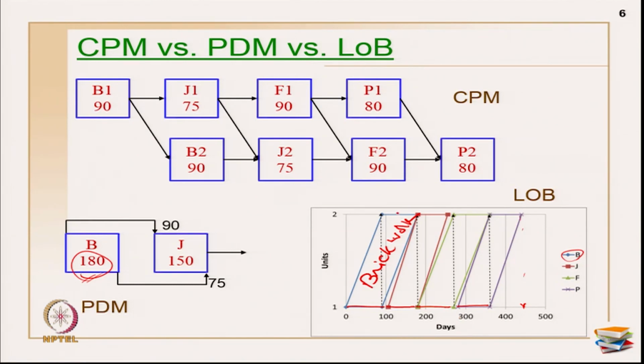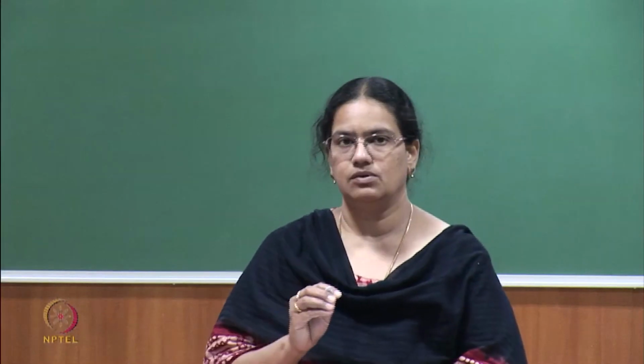The same thing is happening in unit number 2 also. So, first brickwork, then joinery, then I am having flooring activities, and then I am going to do my painting activities. So, the logic of the relationship in standard CPM notation or PDM notation that you have followed should be maintained in all the units. That is the number one condition I would say that you have to maintain.